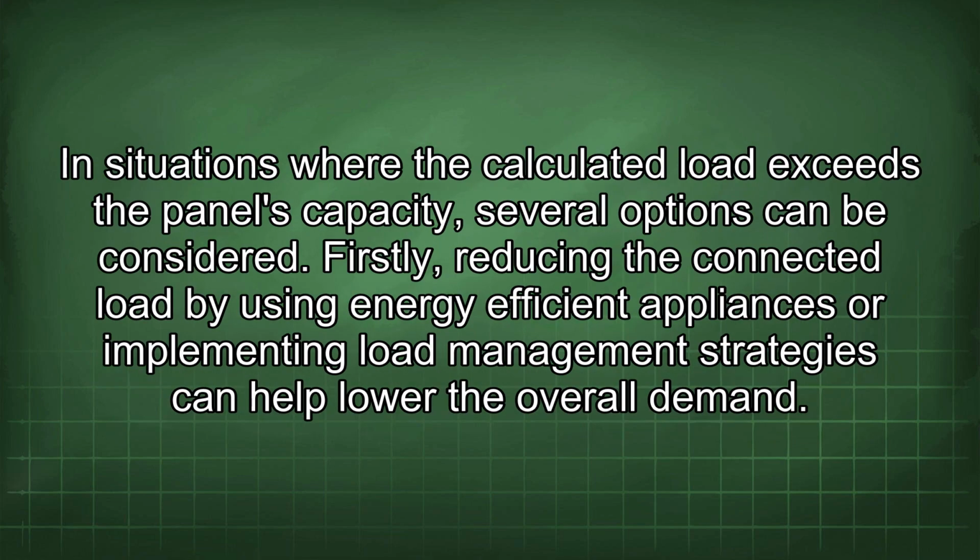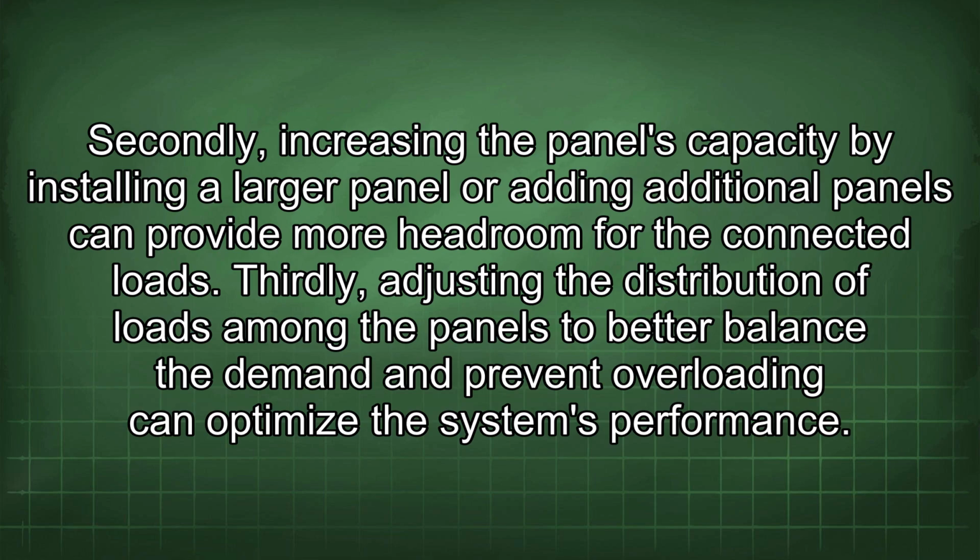In situations where the calculated load exceeds the panel's capacity, several options can be considered. Firstly, reducing the connected load by using energy-efficient appliances or implementing load management strategies can help lower the overall demand. Secondly, increasing the panel's capacity by installing a larger panel or adding additional panels can provide more headroom for the connected loads.